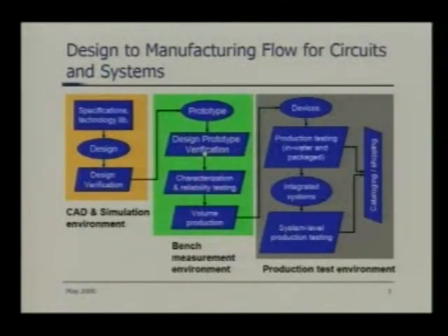So you have to do the design prototype verification on board, okay? On board meaning on PCB. So you have to fabricate some sort of test fixture on which you can mount your prototype IC so that you can connect the IC to the test signal generator, for example, say function generator. You can connect the IC to the oscilloscope so that you can see the response waveform.